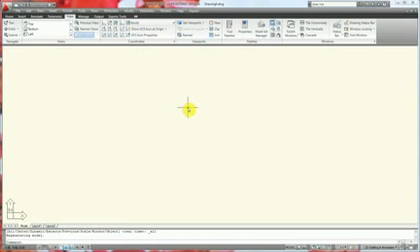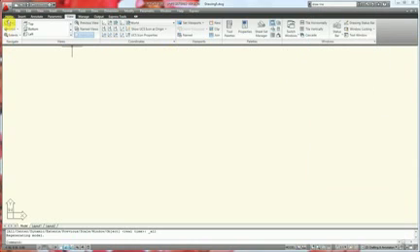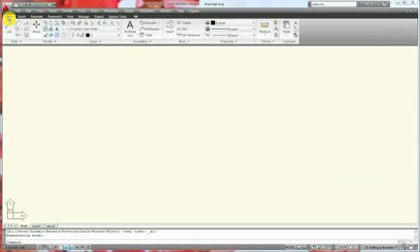Next thing we want to do is start to draw a line. Now anytime you aren't quite sure on how to start a command, you can always go up to the bar up here and type in either a question or just a simple phrase or keyword. So in this case we just type in draw a line, press Enter, and this menu will pop up. And you can go through this menu and it'll walk you through the steps to answer the question that you give it. So I'm going to get out of this, and we're going to go back to the home portion of the ribbon tool panel, and we're going to simply left click the line button.